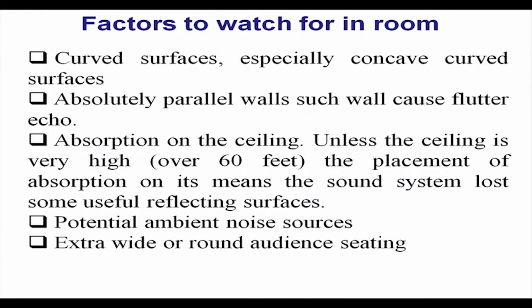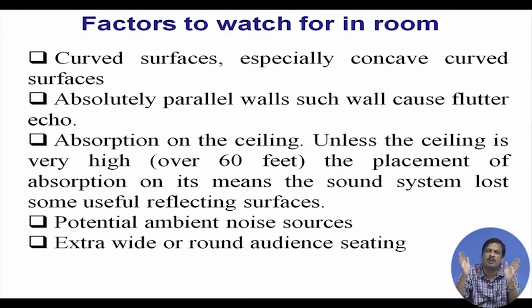Next, factors to watch for in a room. What is the meaning? When you design an acoustic studio, which factors should you look at? First is curved surfaces, especially concave curved surfaces. There should not be any concave curved surface. Okay. Then absolutely parallel walls, such walls cause flutter or echo. When you design an auditorium, there should not be two absolutely parallel walls.